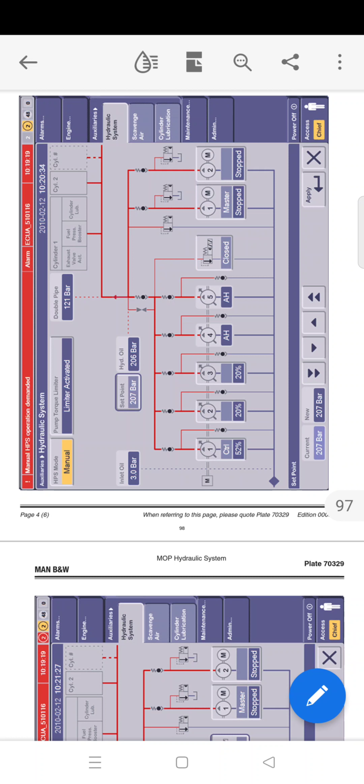At normal running with the SPS mode in auto, the bypass will open in the event of shutdown of the engine. Because after shutdown, the engine may keep on windmilling, that is the propeller continues to turn, and in that case the attached pumps will also be running and they will deliver, because these are positive displacement pumps. It will continue to deliver oil, but this oil is not being consumed in the fuel booster unit and exhaust gas unit, so ultimately it will overpressurize the line and the line may rupture on the delivery side. So oil return is very much required from the delivery lines of the pump.